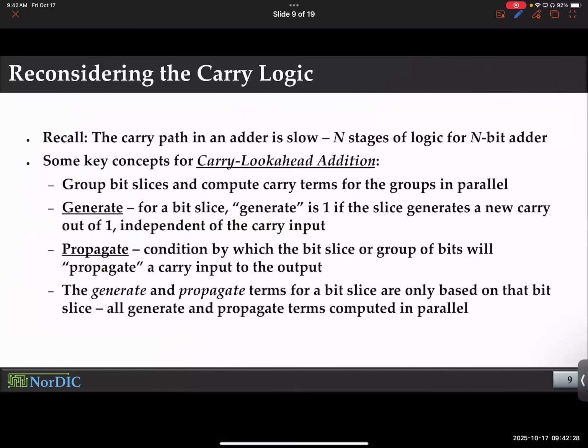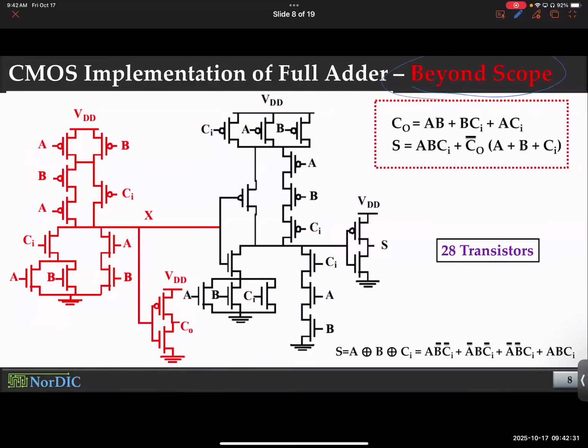Okay, so now remember one thing, folks. Whatever is carry out for one stage will be the carry in for the next stage. So today's carry out is tomorrow's carry in, basically, right? So this carry out signal is kind of, let me ask you a trick question. I'm trying to interview you, for example, as an Intel hiring manager. I'm trying to hire you as an intern. I ask you, just look at this circuit. How many capacitors will this carry out drive, at least? In your knowledge, how many capacitors will this carry out drive?